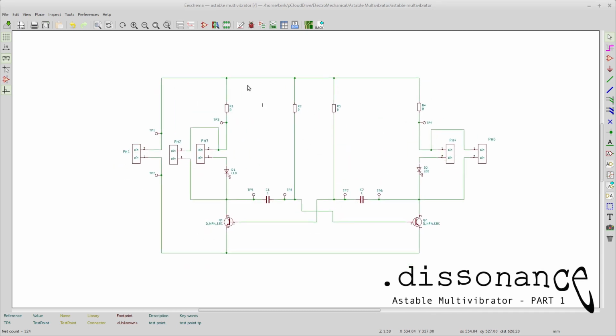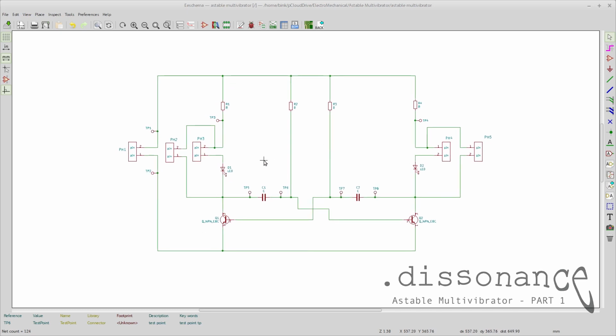So the next thing then, after annotation, is electrical rules check, and then we have to do the association, and then run our netlist, and then we'll move on over to the PCB editor. We probably will go there and probably come back here because there's probably some more things that get kind of messed up along the way.